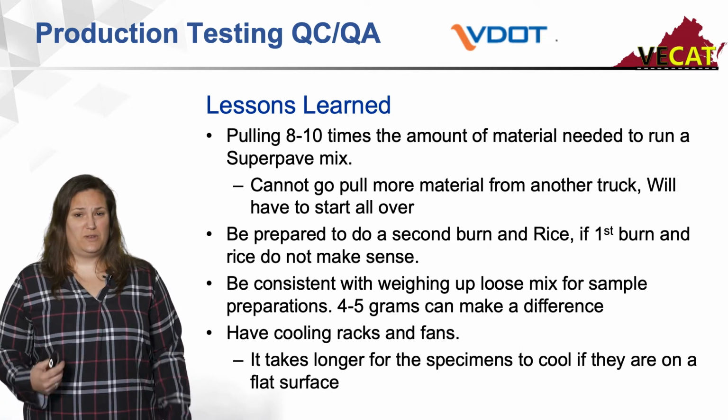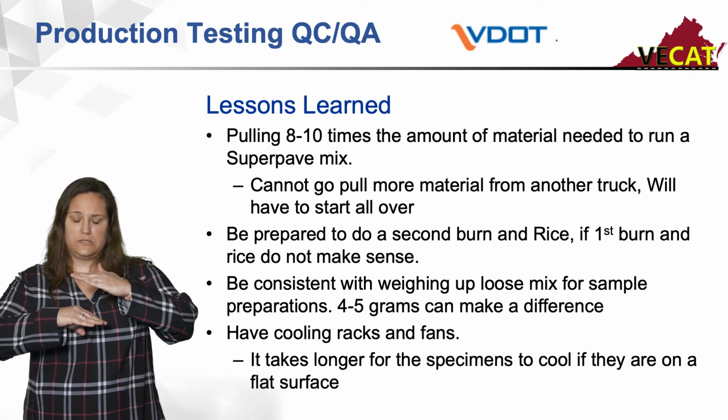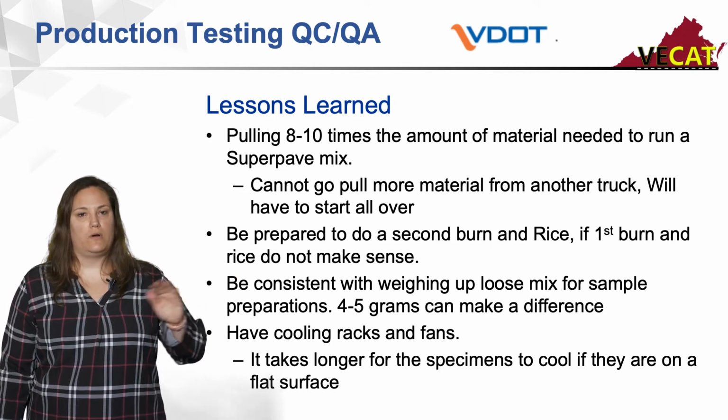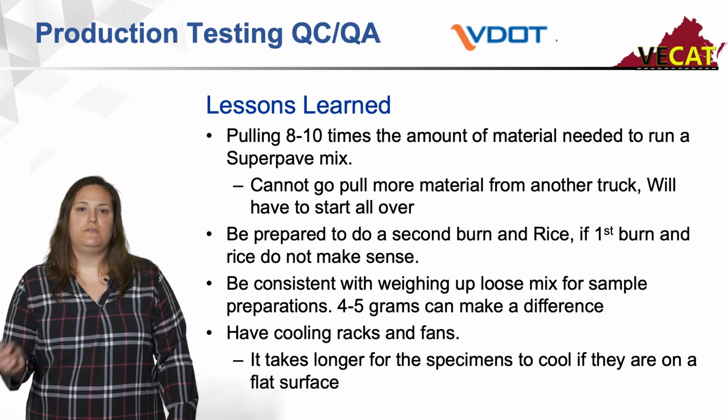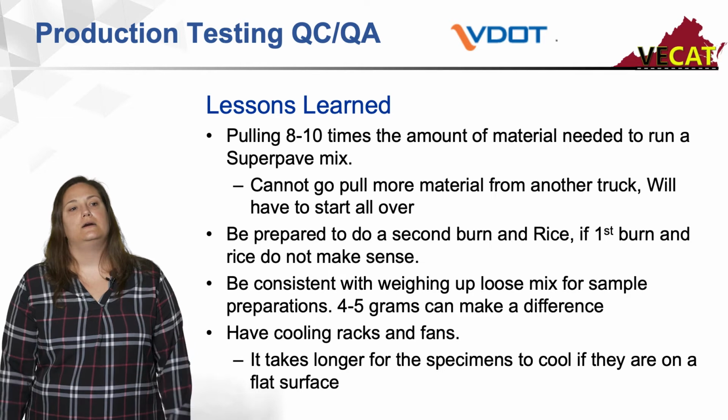Be consistent when you're weighing up your loose mix, because when you're compacting such a small type pill, 5 grams can throw off a whole % void. So if you found what really works, make sure you're really consistent with that.